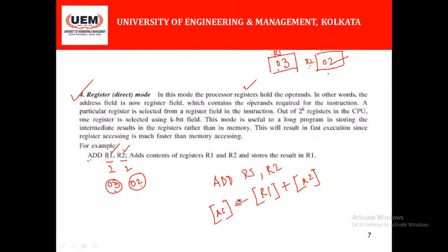Okay, inside the register R1. Very sorry, this will be stored inside the register R1. This is our first source operand, this is our second source operand, and this is where the result is stored. Our first source operand is 03, the second is 02, and 03 plus 02 is 05, which is stored in R1. Look at that, the operand is in a register specified in the instruction. So if we go directly to register R1, we can get the data.